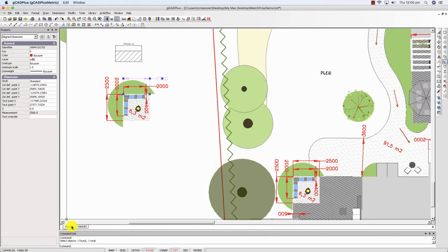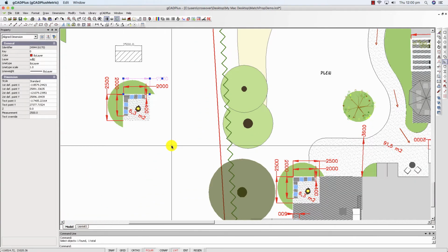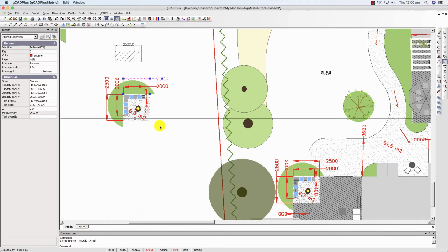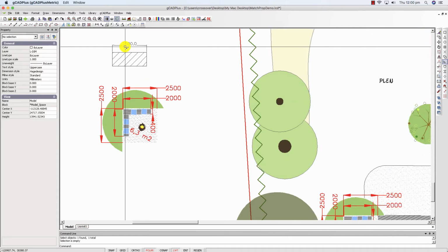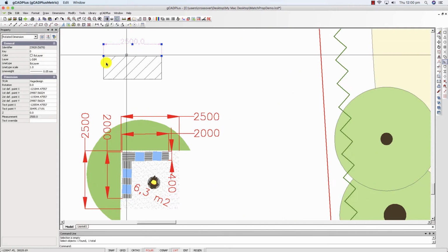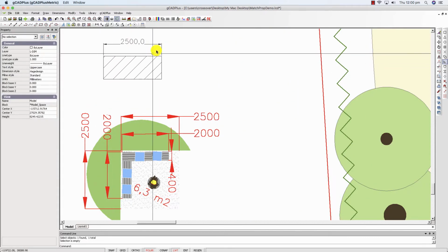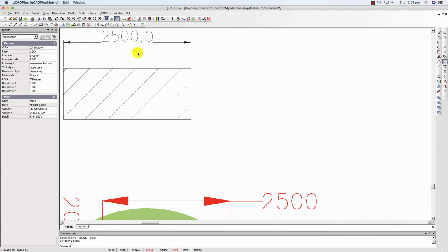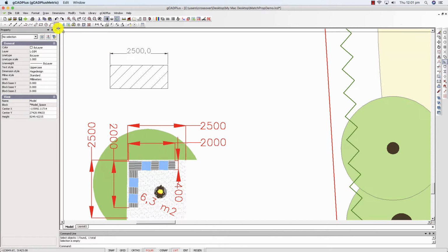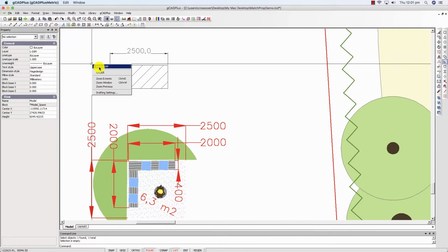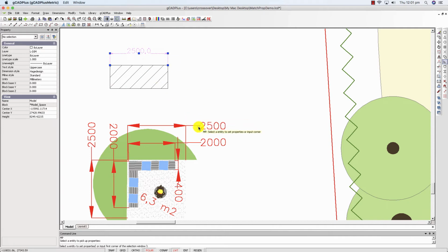Let's come back here, and it's in a style called standard, but we might want it in a different style, and I've made a different style here. I've called it Hager Design, and I've used the European comma in the dimensioning, and the style is set for 1 decimal place. So we can simply match the properties of that dimension style to others here, and you can see how easy it is.